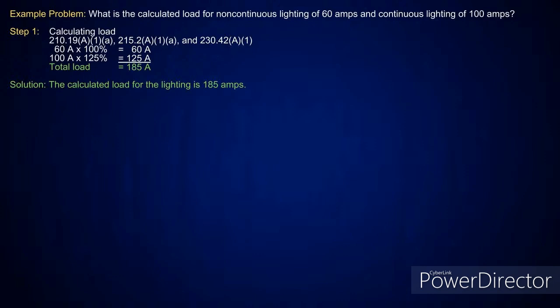So let me give you an example. If I took 20 amps at 80%, that gives me 16 amps. If I took 16 times 125%, that gives me what? 20 amps. Right. So the 125% is already taking care of the 80%. So if somebody comes up and tells you that's what it was based on, they got rid of that 80% because it was being misapplied. So they took that out of the code. All right.